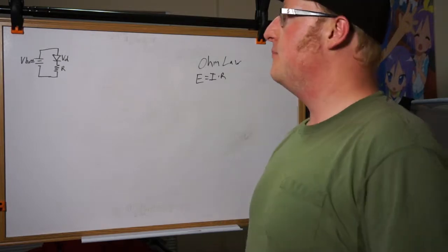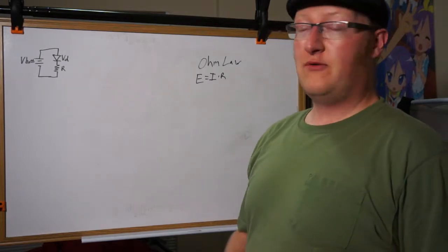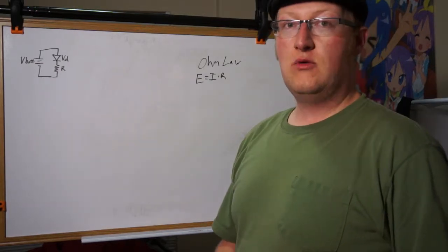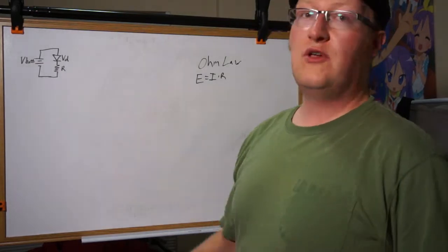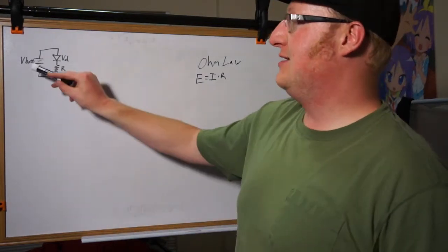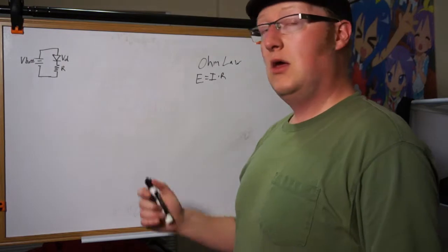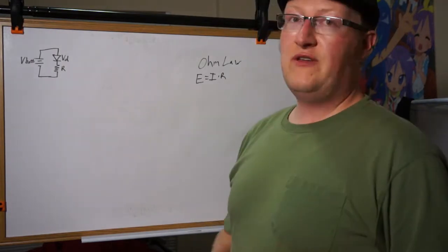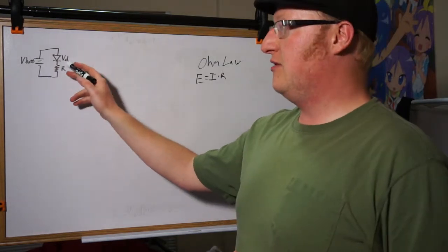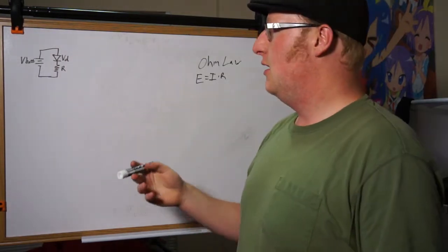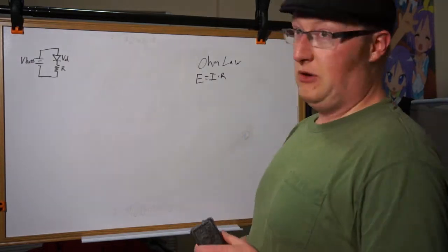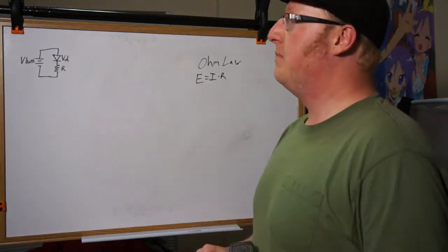So if you remember last time around, or if you haven't, great review, this was the simplest possible circuit. We talked about solving out for the resistance using Ohm's law. We talked about Kirchhoff's voltage law, which says that all the stuff over here has to add up to what you have over here. Now, the problem is this is inefficient. In the last one we used 9 volts, a 3 volt LED, which meant we had to waste 6 volts of electricity through that resistor. This is not the most efficient way of using our energy, not by a long shot.